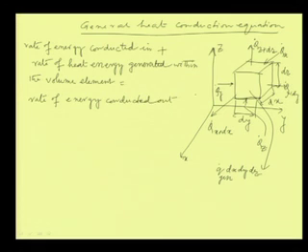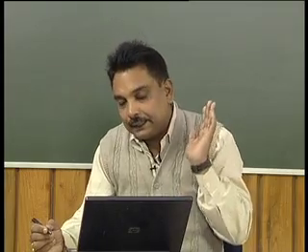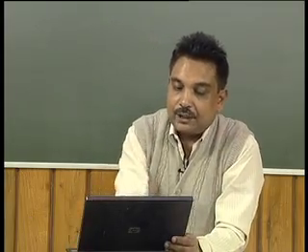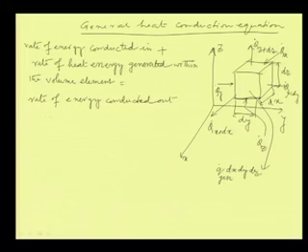Mind it that we are taking care of only the conduction mode of heat transfer, there is nothing else happening in this volume element. So, rate of energy conducted out plus the rate of change in internal energy or rate of energy accumulation within the volume element.